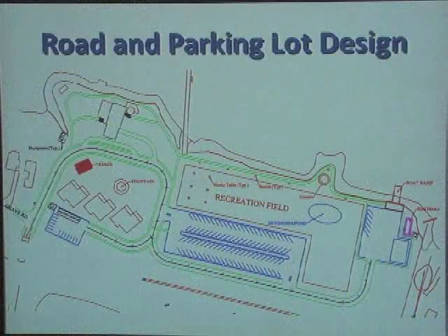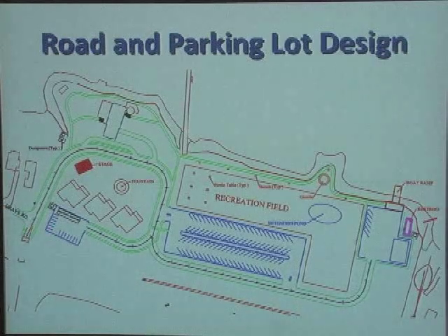My name is Chris Elmer, and I was one of the transportation engineers. As Jeremy said, one problem we had was that our site needed 2 emergency exits for emergency vehicles. As you can see here, there was an existing gravel road adjacent to our site. Just over the bridge, we had no problem tying into that road because we did not need to bring much material here, so they're the same elevations. As the road comes down, this whole portion of the road and back parking lot will be paved and impervious, whereas the large parking lot and the boat ramp lot and the back road will all be pervious material.